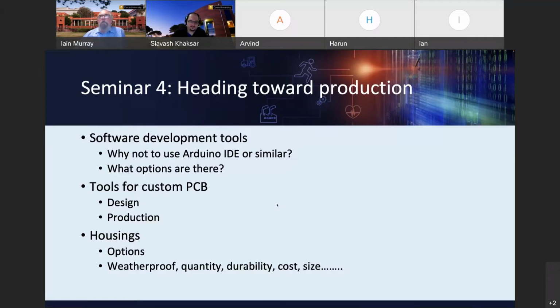And this is building something that will look like your end product. This is possibly working and also possibly doesn't work. It can be for the physical attributes of the system that you've developed. You want to build a mock-up of it, look at whether it's actually going to look as it should. If it should fit in the environment that you're going to put it, you might do it for testing of weatherproofness, adaptation to other pieces of equipment. So if it's an add-on to something else, and you want to build something that is physically correct, but may not necessarily work, that we'd term a manufacturing prototype.